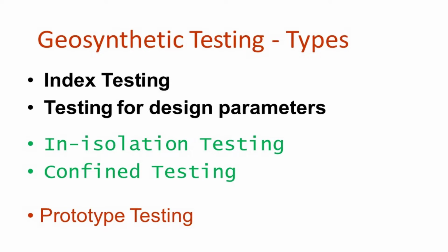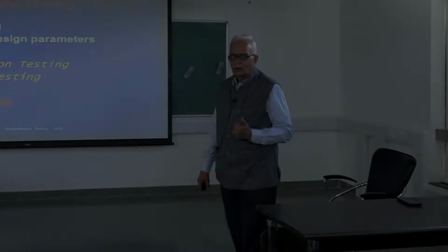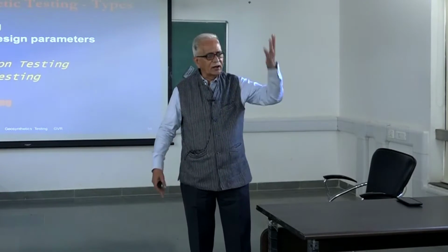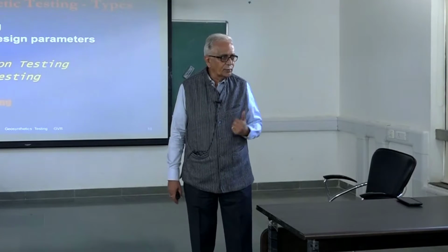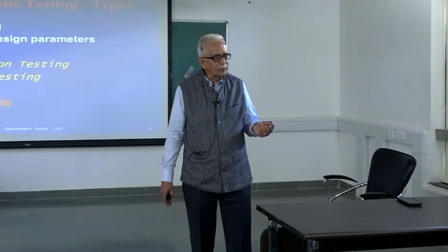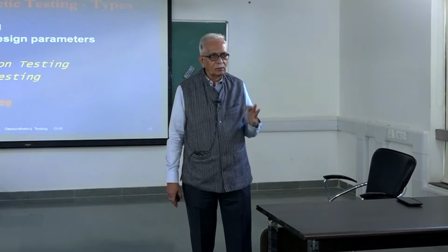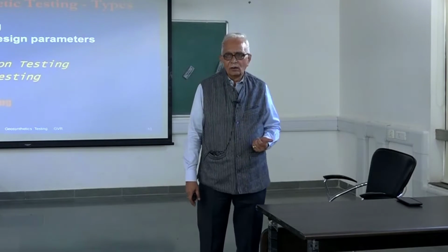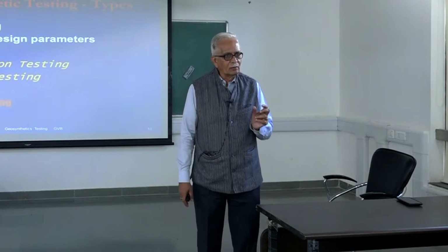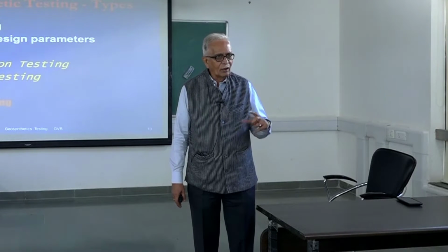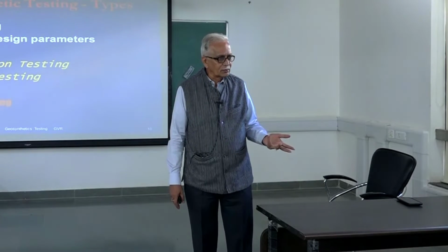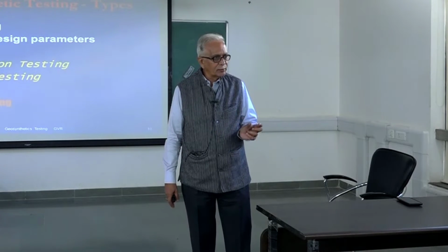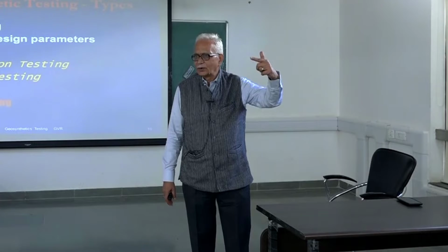Then there is another kind of testing which you look at, which is called index testing. The issue of course which you are going to have is, we got such large widths and large lengths basically. Now if you take a sample, how small should you take, how big should you take? Very difficult. So for example, if you look at the strength part of it, the test engineers are used to using widths and lengths in inches, 3 inches, 2 inches like that. So 3 inches long and 1 inch wide. 1 inch means 25 millimeters, 3 means 75 millimeters roughly.